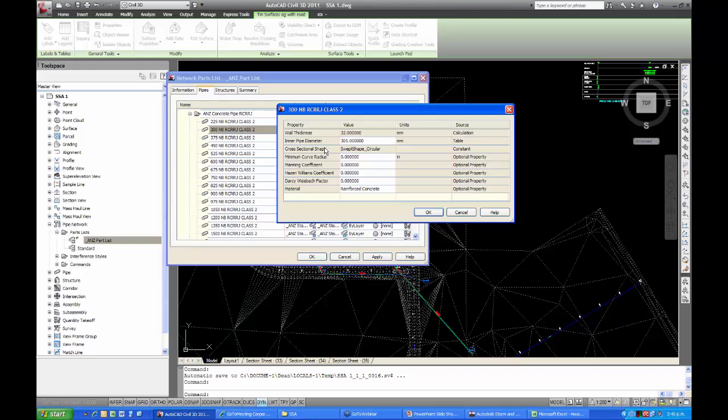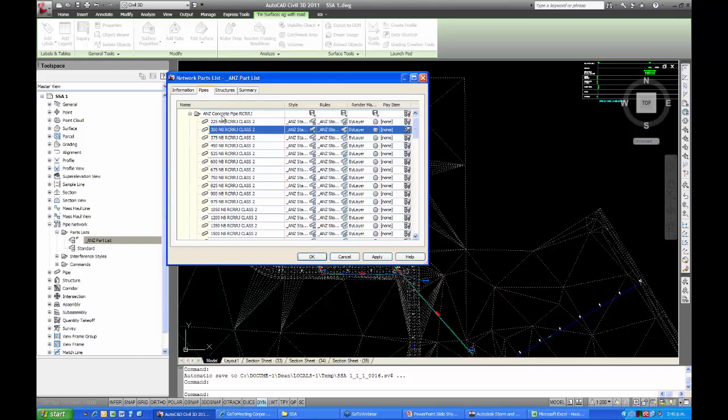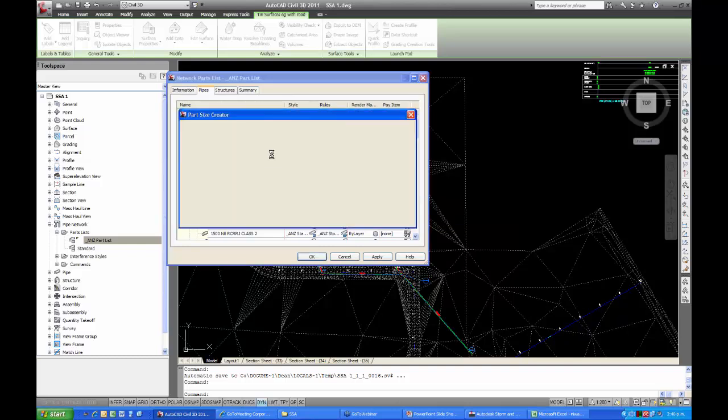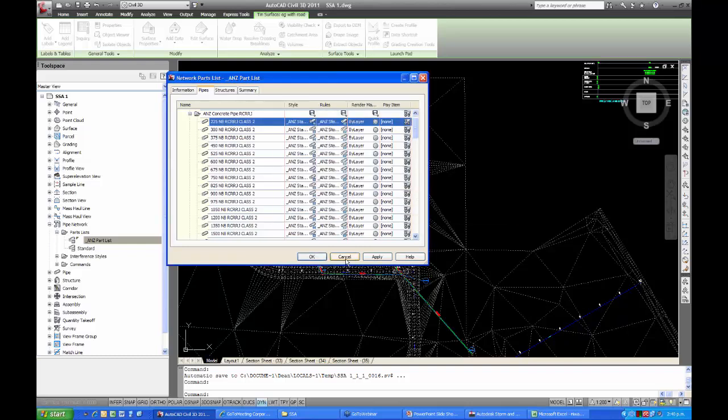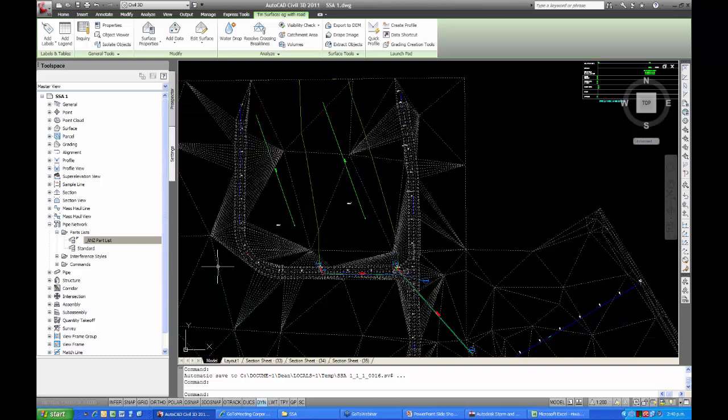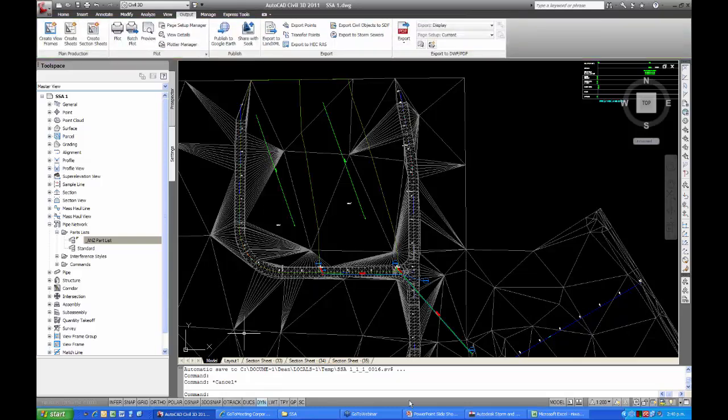All right, so that's where you find it in Civil 3D if you're looking for that. So you need to match that size. For us, we're talking about the 225 pipe. Edit that, and you can see it's 22.2 centimeters, as we've already found out from StormNet. Let me just cancel out of there. Escape out of that and go back to StormNet.